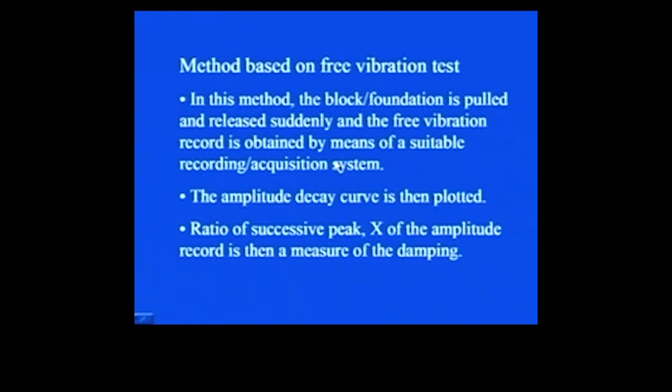Then there is the method which is based on free vibration test. In this method, the block or foundation is pulled and released suddenly, and the free vibration is recorded by means of a suitable recording and acquisition system. See, as the name suggests, in the forced vibration system, the oscillator was mounted to give the excitement to the system, that was a forced vibration system.